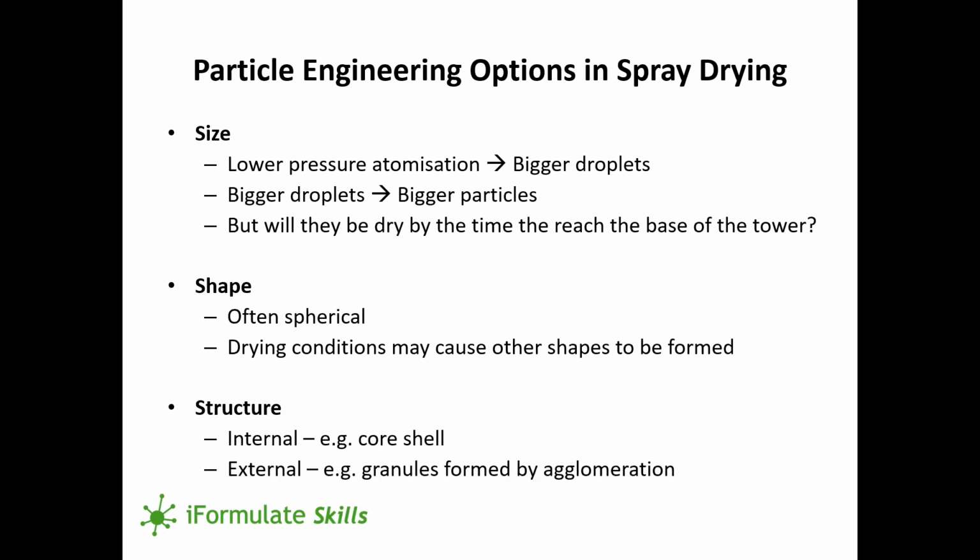And then structure. We can build internal structure, for instance core shell structure, using spray drying, or an external structure by agglomerating particles together to form granules.